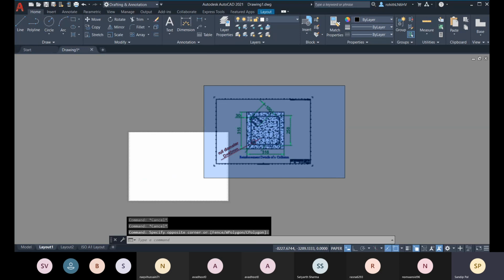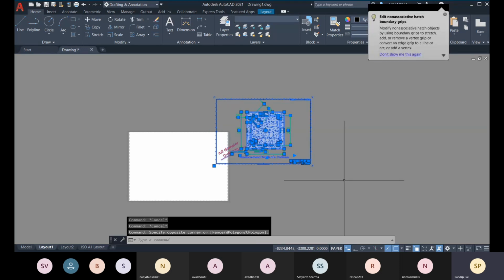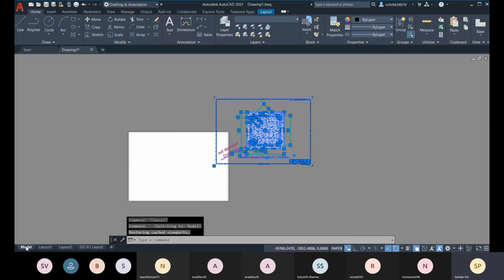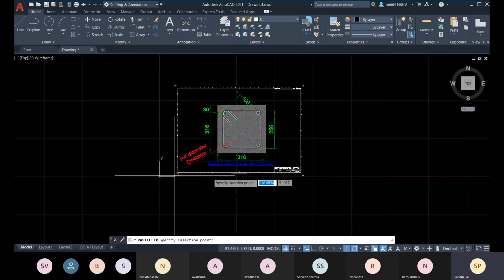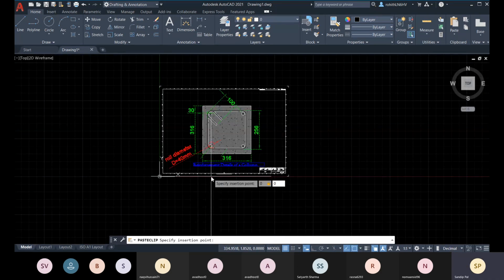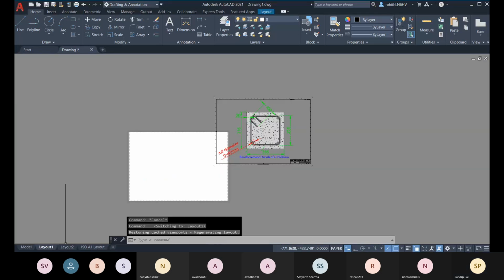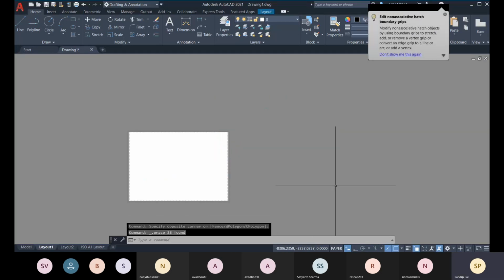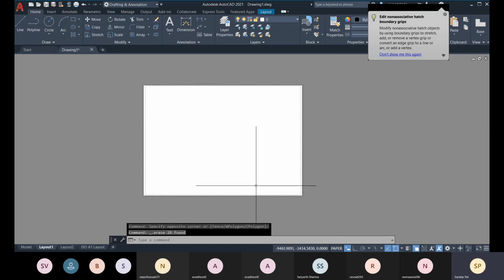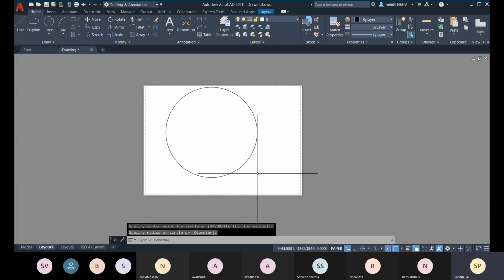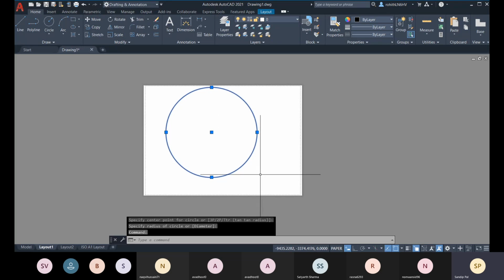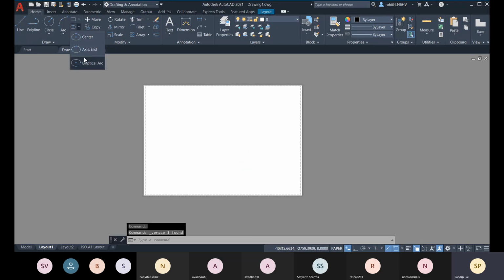Okay, so these are not available within the viewport. Sorry, I forgot that. Here, let me go for Control C, copy them, and Control V, here I'll paste it. Let me paste at 0,0, enter, and here I'll delete it. Okay, and here let's go for that viewport. Let me show you something interesting: you can create a circle there, or any ellipse if you need.